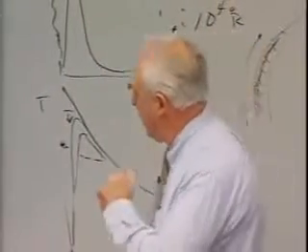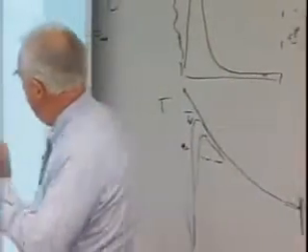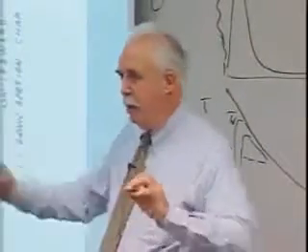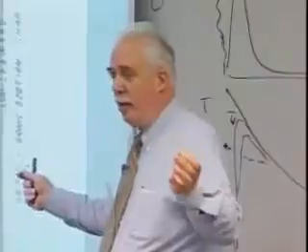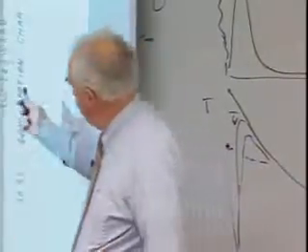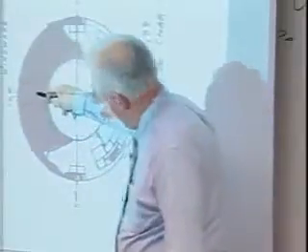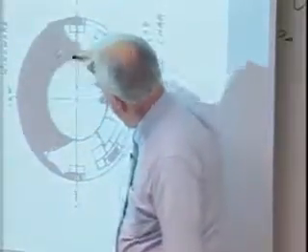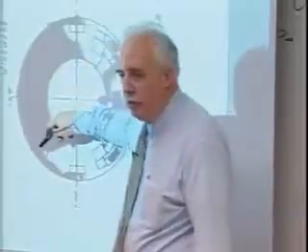Well, one more on the lee side heating. On the shuttle, we had thermocouples located here, there, as many places as the Aerothermodynamics could put them in the TPS guides, but we couldn't put them anywhere. This is the 201 vehicle, and it's on its side. I apologize, that's because of my chartsmanship. The vehicle's coming in at angle of attack on here. This is the windward side where there was charring.